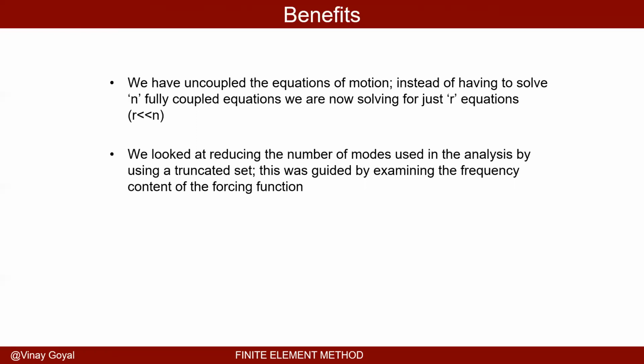Now, let me summarize it one more time. So I have many degrees of freedom for an aircraft. I'm going to use maybe, say, 20 of those modes. What I'm basically telling you is that instead of solving all those degrees of freedom, I can just solve the equations using 20 of them, perhaps. And they're uncoupled too. So, what a powerful idea, right? There are some errors introduced, and it works for linear systems, but it's still very powerful.